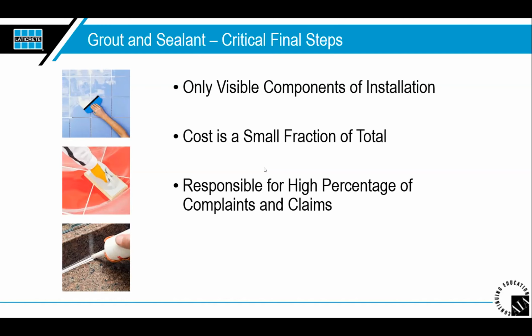So it is interesting how the industry is changing, and people are understanding that sanded and unsanded caulks really don't have a place in the specifications anymore. Okay. Failure to put silicone in the actual corners, coves, and change of planes is going to result in cracked grout and possibly cracked or delaminated tiles as well.